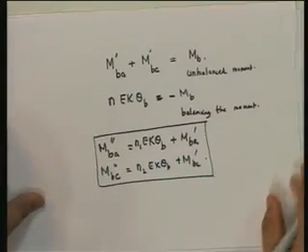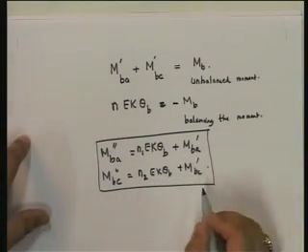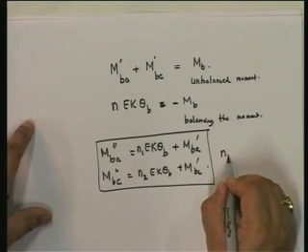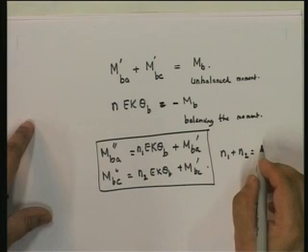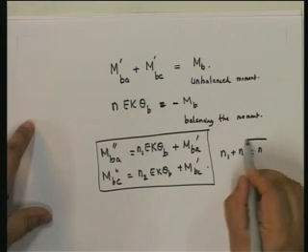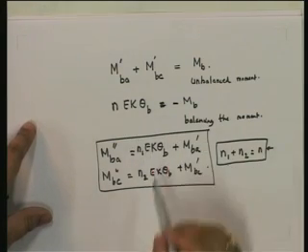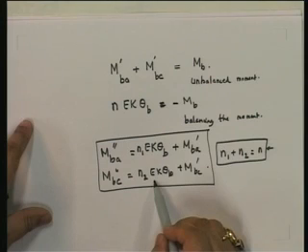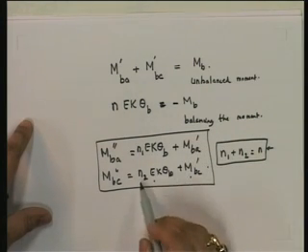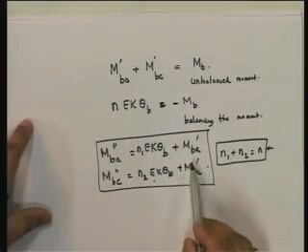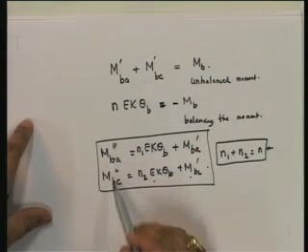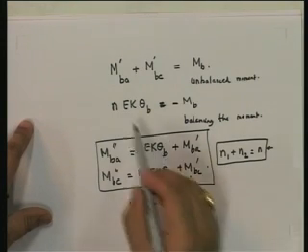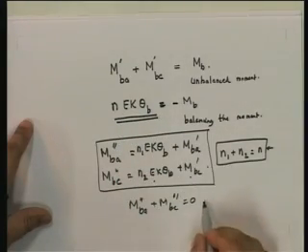And if we look at it, what are n1 and n2? n1 and n2 are numbers, and you will see here, since we are doing MBA plus MBC, that n1 plus n2 is equal to n, because it's this plus this. So if you now look at this, what do we get? This plus this is equal to this plus this. n1 plus n2 is equal to n, but this is equal to minus, and this plus this is equal to MB. So what you get is MBA plus MBC is equal to 0, balanced. So we have released theta B to get a balance.